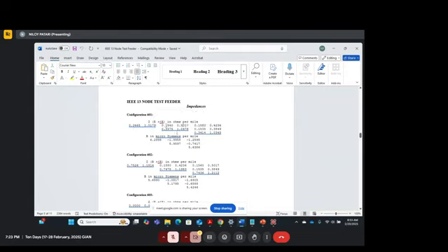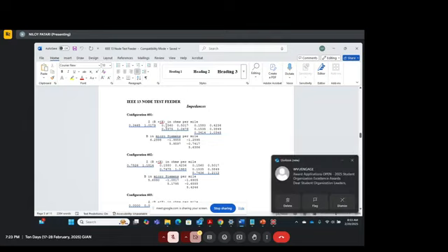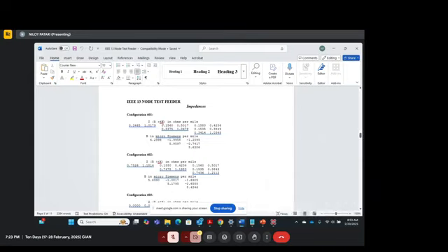It's symmetric, so 1,2 equals 2,1, 3,1 equals 1,3 and all of that. But basically those two nodes are connected by 601 over 2000 feet of length, right? So you get these R and X values and then just multiply them by the length in feet.